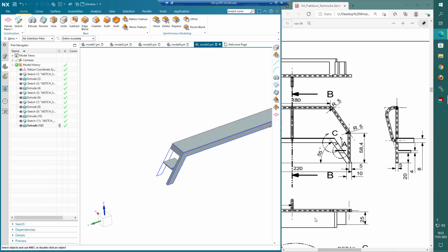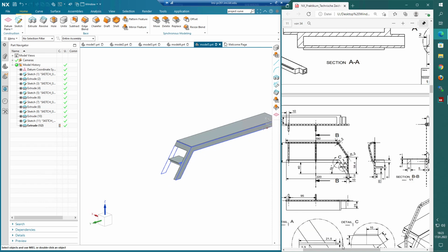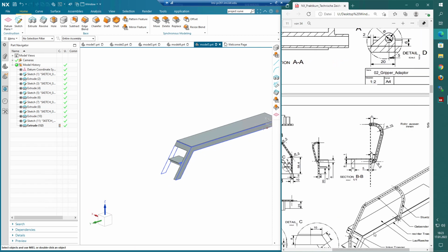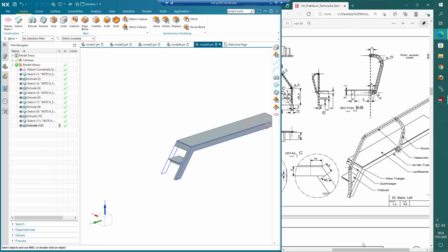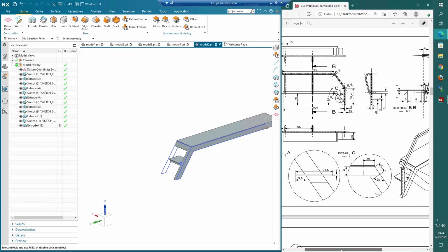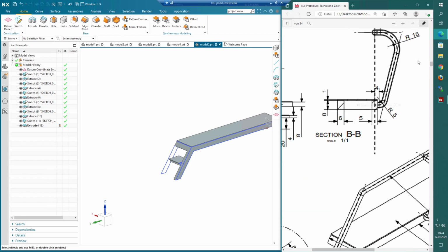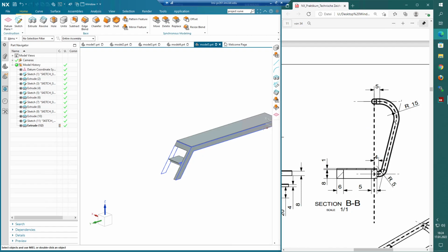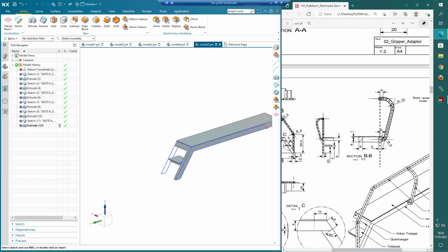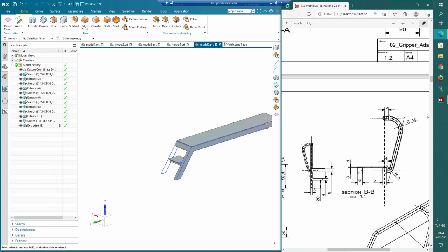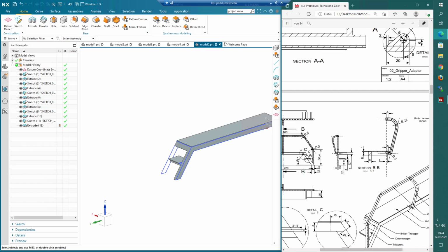So it's looking pretty good, and I think the only thing we are still missing is the handrail. So let's do that, and for that we obviously want to use the sweep along guide function. So we need a guideline and the outer, or a cut, and we can see the radius is 15. No, that's from the guideline. Is it 5? No, that's all measurements of the guideline.